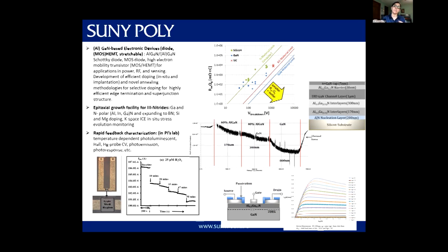You can see that going from silicon to silicon carbide, which is another wide band gap material, an indirect wide band gap, to gallium nitride, you can reduce the on resistance, which is really important. What it provides is the ability to handle much higher voltages because of its wide band gap, but also you can make the device much smaller.